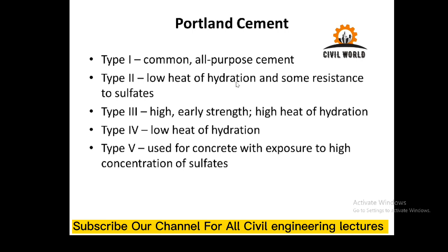So they exert internal pressure in concrete, leading to cracking and reducing its strength. To guard against those sulfate attacks, type 2 also provides some sulfate resistance, but the major advantage is that they are low heat cements.